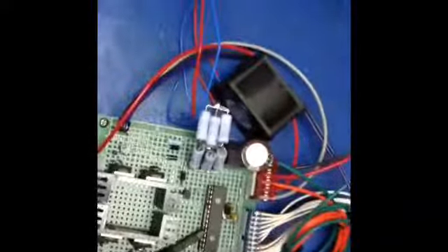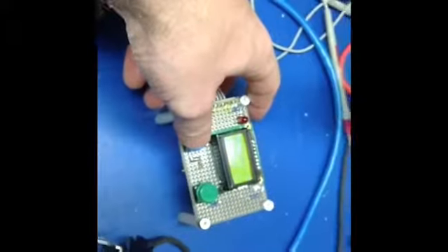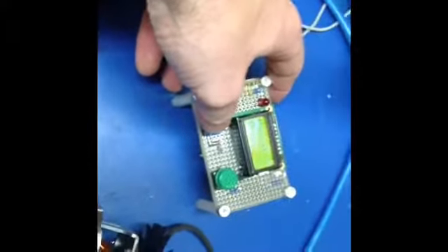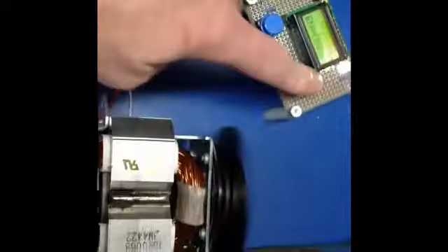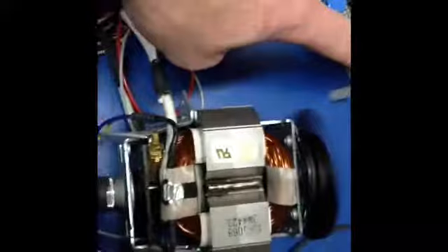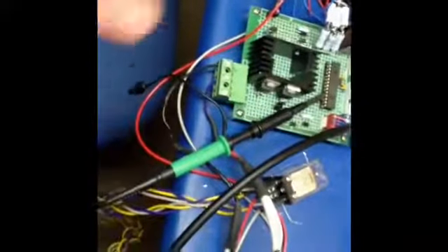So turning it on, that's the fan noise. And I've got my little program here, blue for manual, and so I'm in manual mode now. And if I push it, I get my motor to spin one direction. And I've got a relay here that allows me to switch the direction. Again, this is a universal motor, so I have to reverse the windings to make that happen. But in the next video, I'll show you what the exact circuit of that is and how it works.